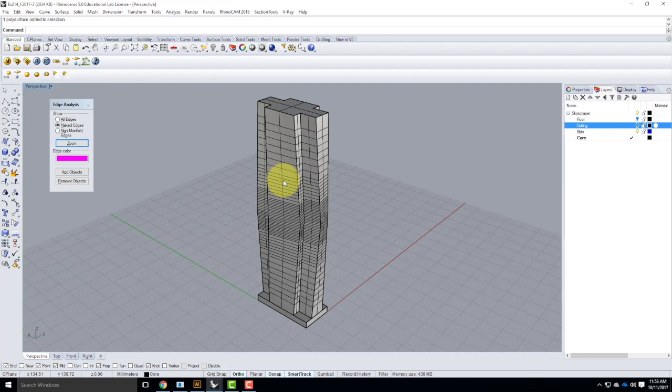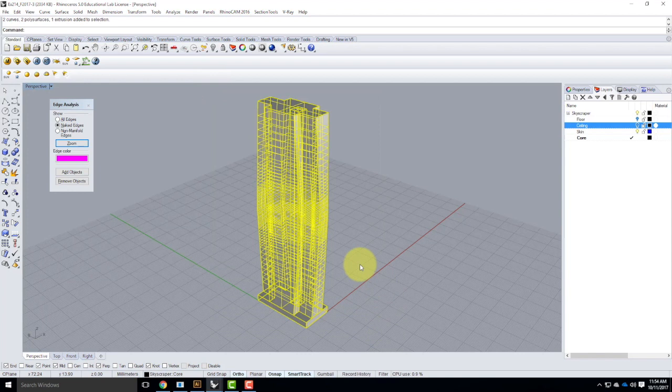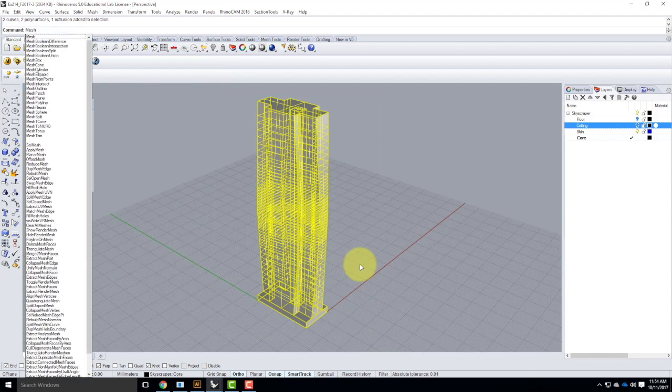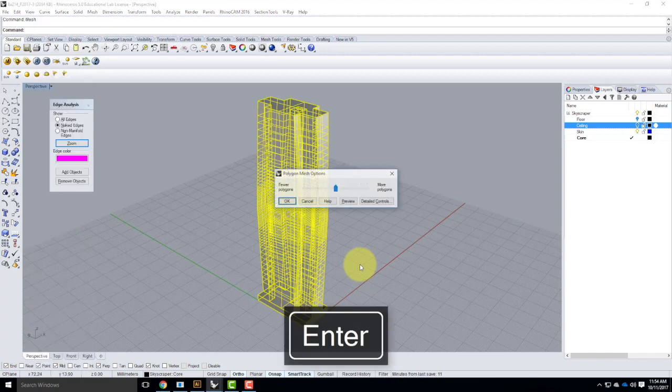So we're going to convert this over into a mesh before we leave. Now, we could do the conversion as we export the file to go, or we can do the mesh conversion before and see in preview, does it look the way we want it to do. So I would encourage you to do it ahead of time, which is what I'm going to do. If you select your object, there it is, we will just type mesh, which is essentially the command to convert to a mesh. I'll hit enter.